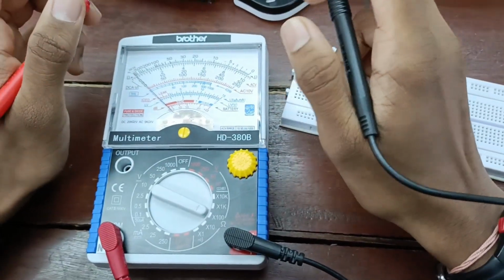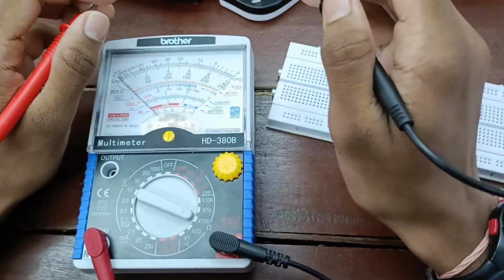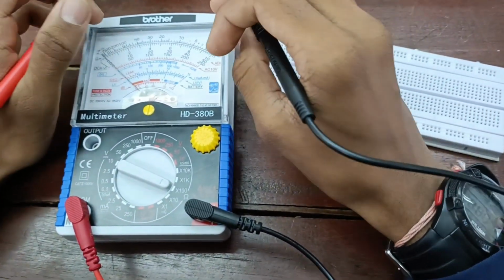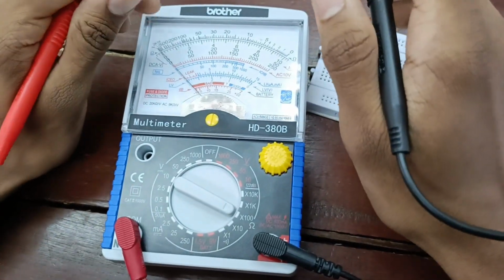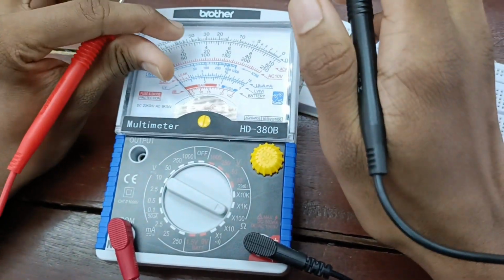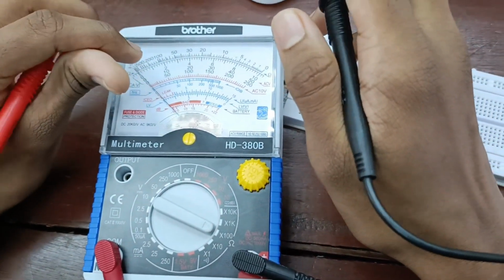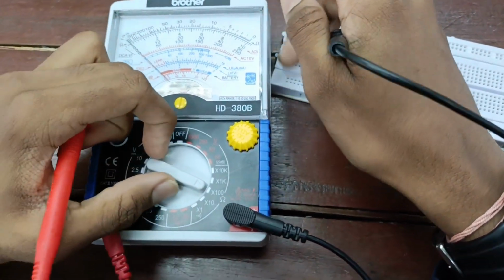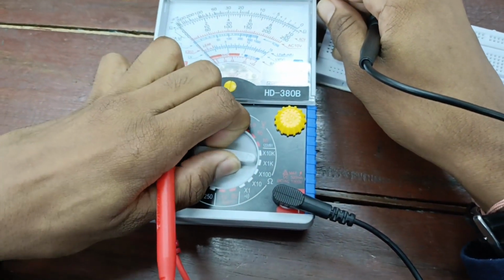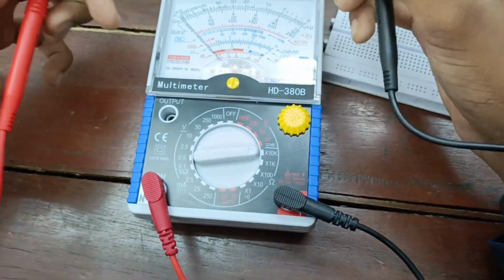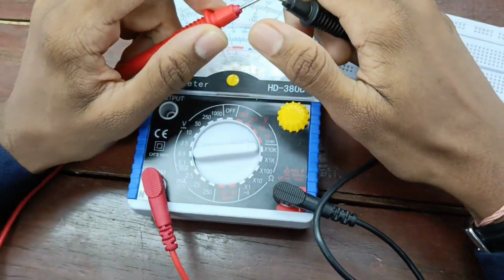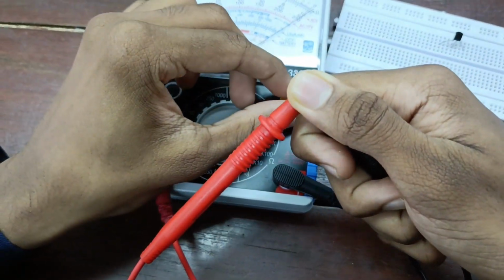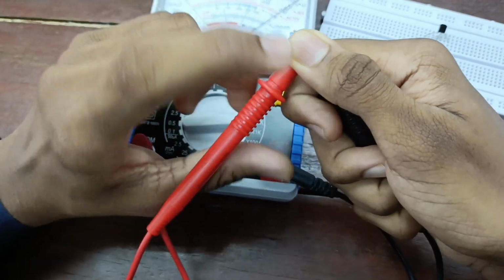So guys, for the next one, we are going to see how to identify the collector or emitter terminals in our transistor. For that, first of all, we need to change our ohm range to a higher range, for example times 100k, or a higher ohmmeter scale. So I'm going to choose times 10k, and now we need to do the calibration at the multimeter until the pointer reaches 0 at the ohm scale.